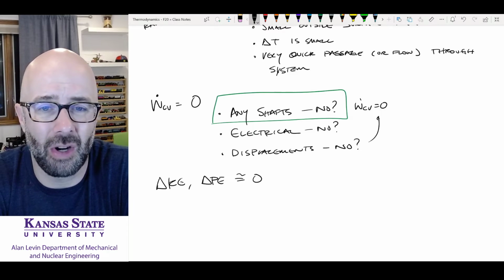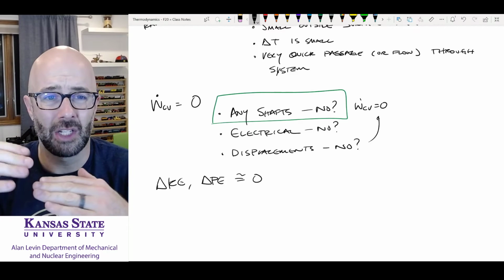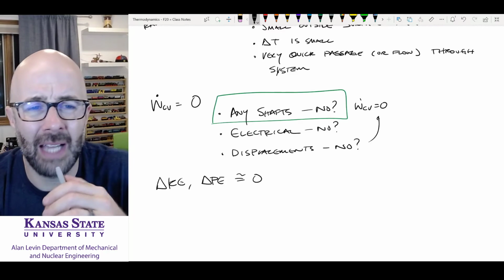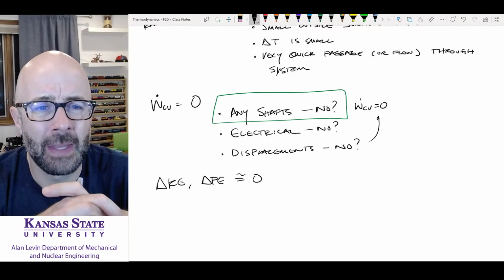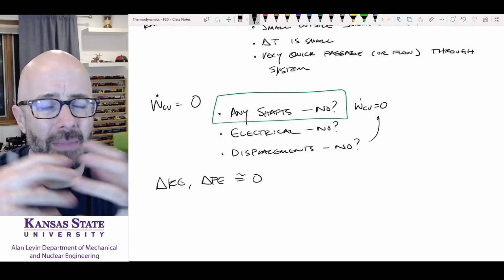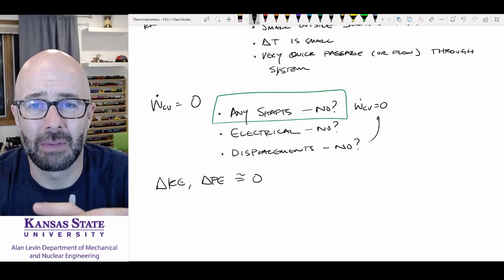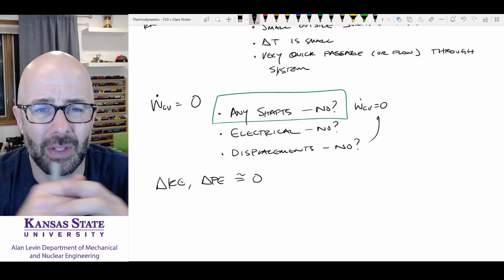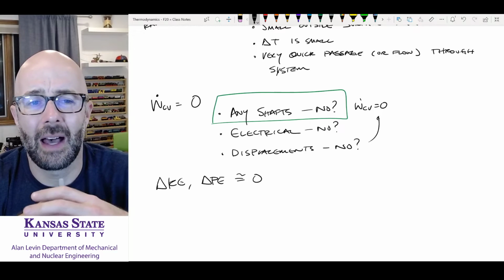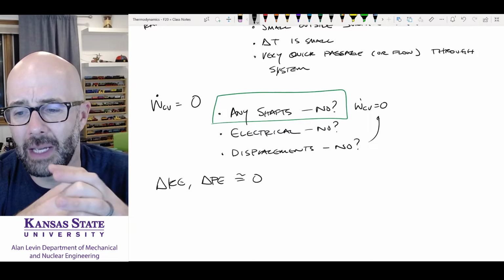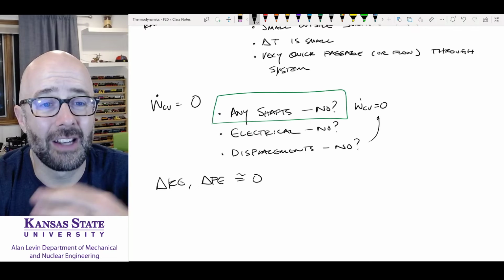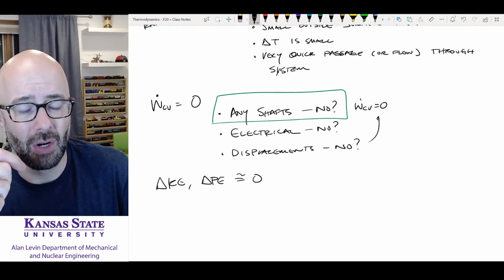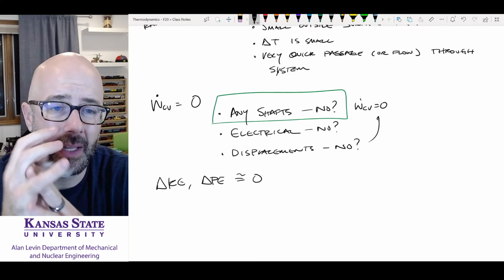Potential energy changes are going to happen when we're dealing with pumps. As you're pumping from a low altitude to a higher altitude, that's the only time really we're going to be dealing with potential energy. Kinetic energy could happen in almost any problem, but as we'll see from calculations, that's usually a very small number. It usually only becomes an issue in nozzles and diffusers, which happens to be our very first control volume that we are going to be dealing with in a few minutes.